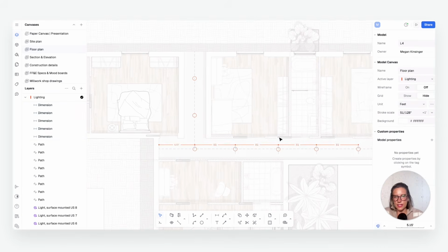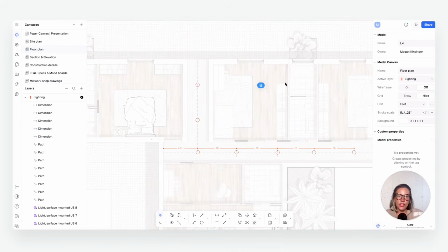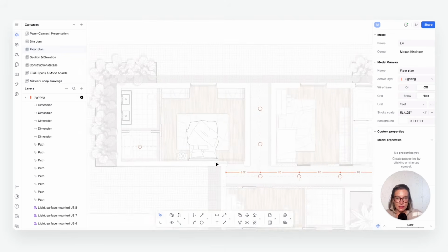And that's kind of how that starts shaping up. So these grid lines help us align our lights with our architectural elements, and then coordinate that with our reflected ceiling plan. Now, when you're placing these, you also want to consider color temperature, whether they're warm, neutral, cool, and you want to avoid any major shadow areas or any awkward fixture placements. So with that in mind, let's go ahead and add in a few other types of lighting.